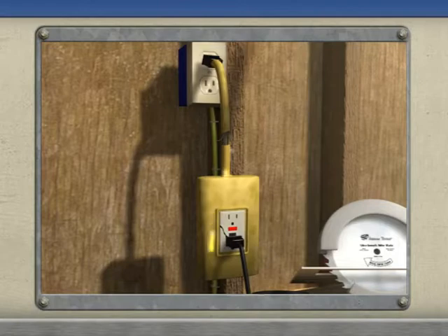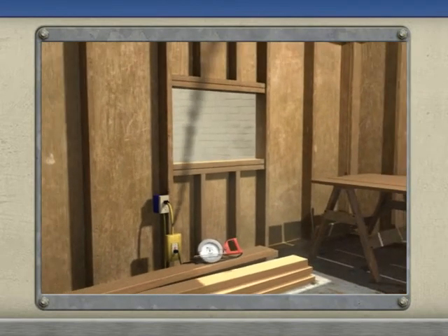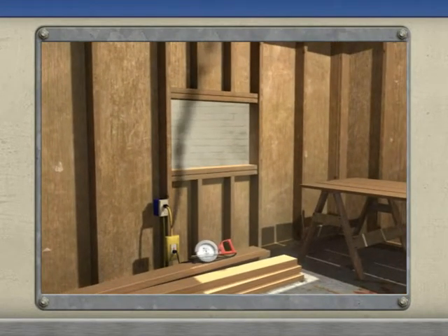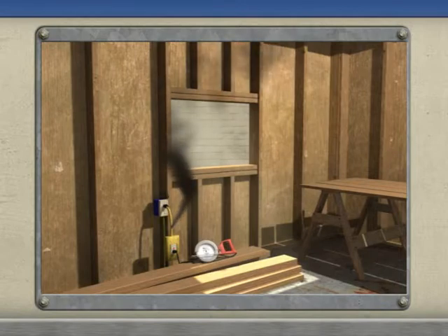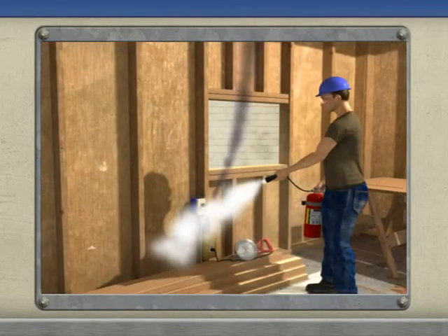In addition to serious injury, defective or inappropriately used electrical equipment can produce heat, which can lead to electrical fires. Electrical fires are one of the most common sources of fires and burns at home and in the workplace. Small electrical fires can be extinguished by properly trained personnel using a fire extinguisher designed to put out Class C fires. All fire extinguishers are marked with the types of fires for which they are designed to be effective. Follow your facility's proper procedures when dealing with fires.